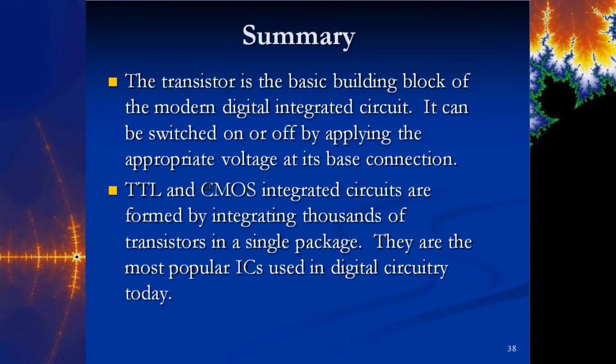And I would say that when I crack open my kids' electronic stuff that makes noise and lights up, more than likely they all have TTL because they're not worried about speed. And they know the kid's going to leave the thing on anyway. So at that point, it doesn't matter if you got CMOS chips or if you got TTL. And so they just go the cheap route and use the cheapest things that they can. So that's what I found when I cracked those open. But if it's something that's a little bit more high tech and they want the battery to last longer, then they would use something that consumes less power.